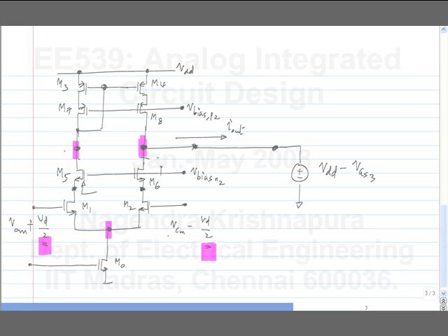Last time we analyzed the circuit, if the differential pair is terminated by small resistances, the tail node voltage is 0. What is the impedance looking up here? 1 over GM5, and here, same, 1 over GM5. So it's terminated by a small enough resistance that this is close to 0 volts.